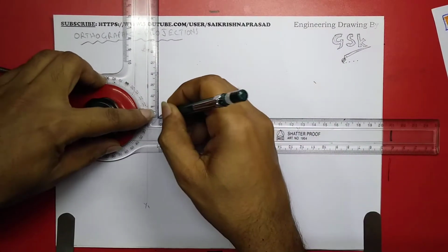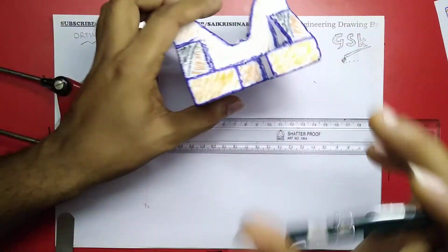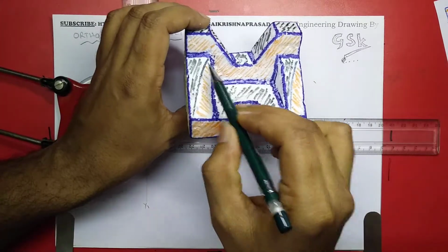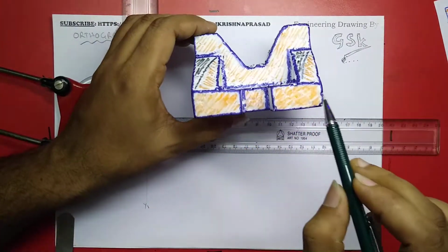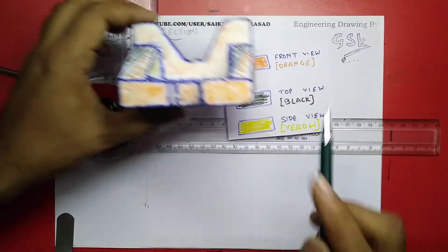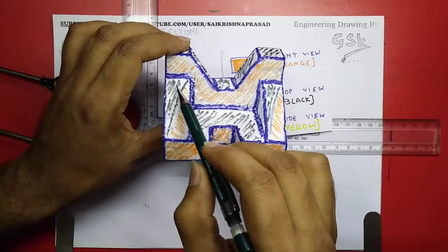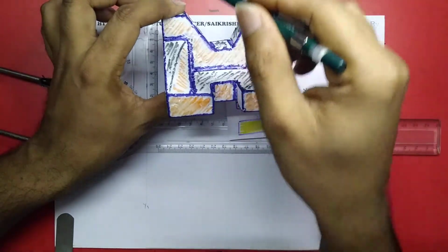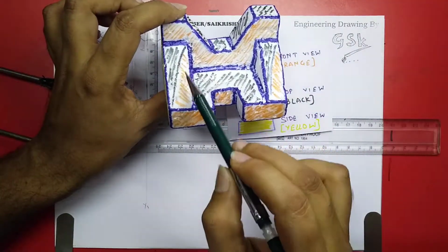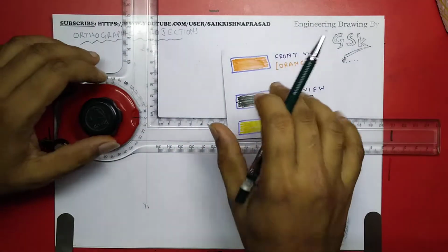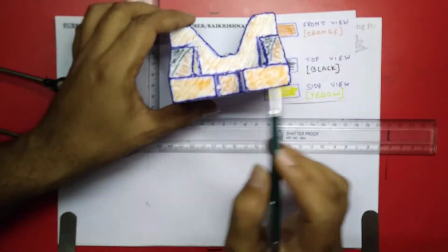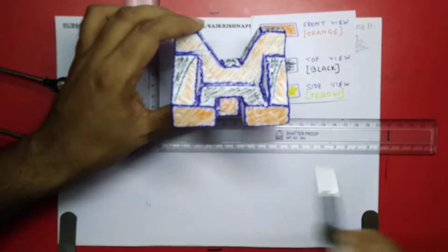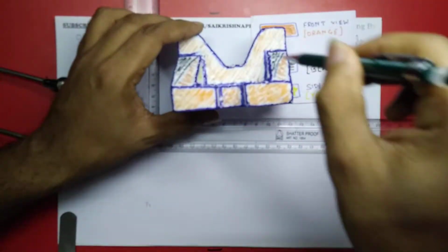So I'll be measuring the length. In front view I can see this edge, this edge, this, all these lines which are shaded with the orange surfaces. I can see this surface also, because this is inclined to our view, but it can be seen from top also. So it has a mixed structure, top and front view. If I number them, this is surface 1, 2, 3, 4, 5, 6. Means in this front view I can see a total of 6 surfaces.